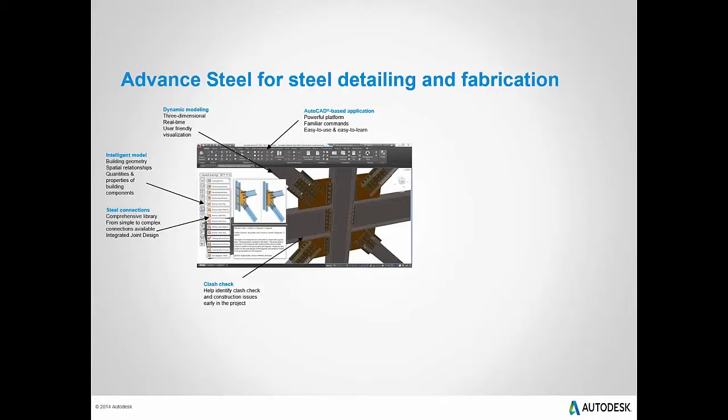But our clash detection tool inside of Advanced Steel is primarily looking for things that maybe is a good checking, in that I haven't got all my connections done. I'm seeing beam flanges that are not yet coped. I'm having members run into other members. So it's effective for that in helping us with the completion of our full project.